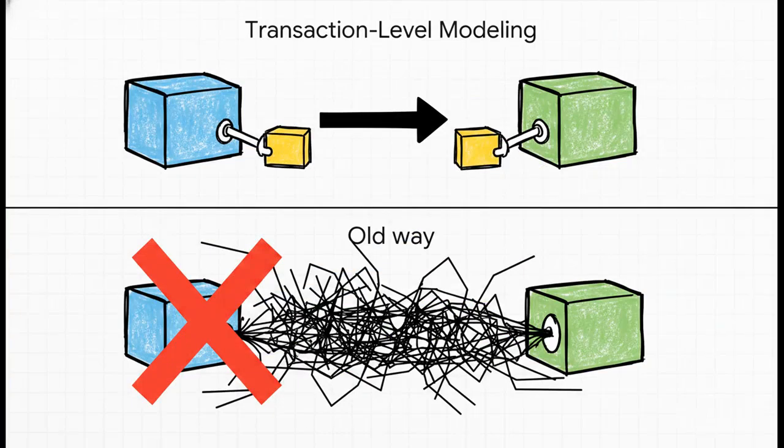Now, during that connect phase I just mentioned, we're hooking up communication ports. UVM uses something called TLM, or transaction level modeling. And here's a massive takeaway. This simply means components communicate using transactions, not individual pin signals. Instead of the sequencer telling the driver, hey, toggle wire A high, wait a clock cycle, then toggle wire B, it just hands over a single transaction that essentially says, send this data packet. The driver handles all the messy signal toggling on its own. This super high level of abstraction, that is the secret sauce to UVM's massive reusability.